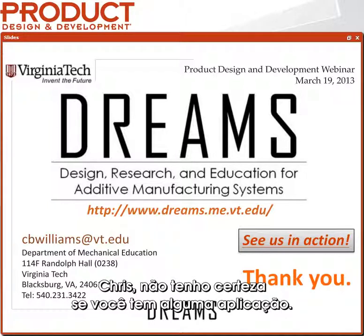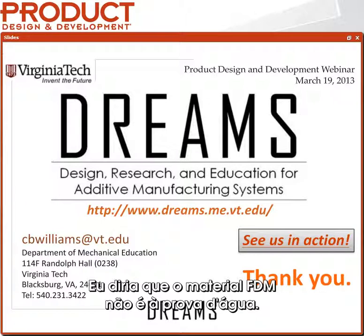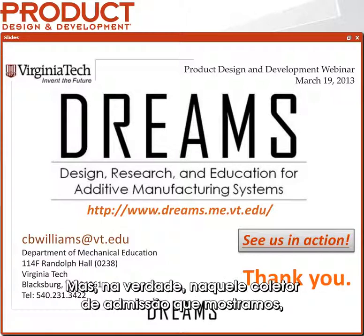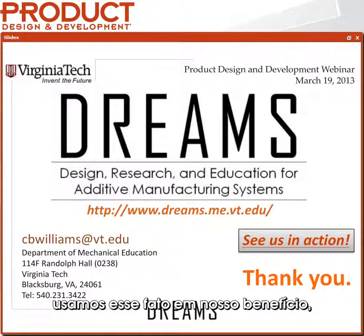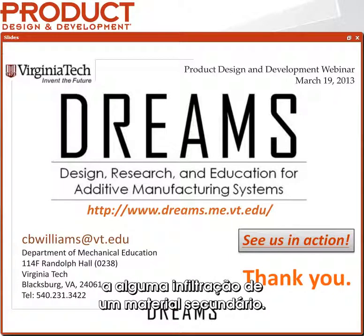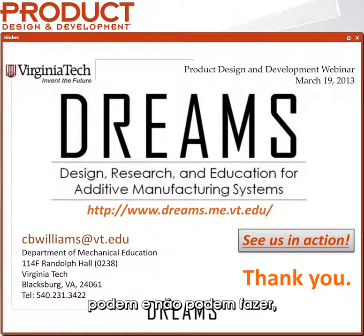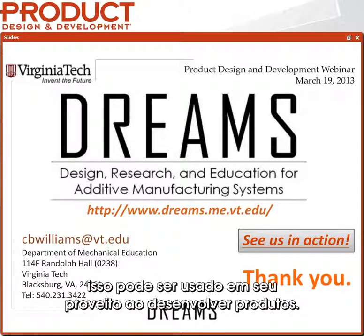Chris, I'm not sure if you've thought about applications, but go ahead. No, that's fair, and I would say that the FDM material is not watertight. But in that intake manifold example that we showed, where we did the carbon fiber layup, we actually used that to our advantage. We knew it was slightly porous, so we knew that would give an opportunity to do some infiltration of a secondary material. So if you know what the technologies can and can't do, you can use that to your advantage when you design products.